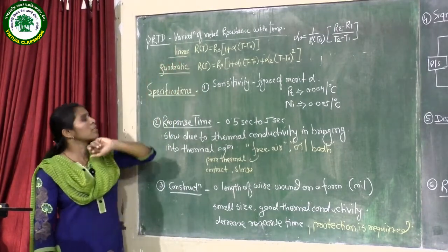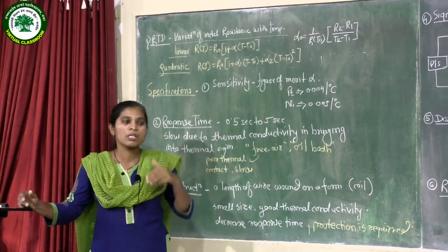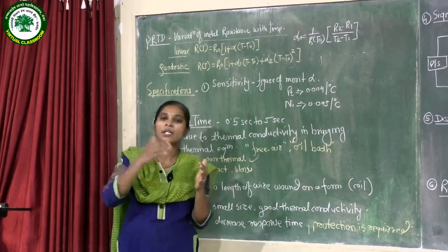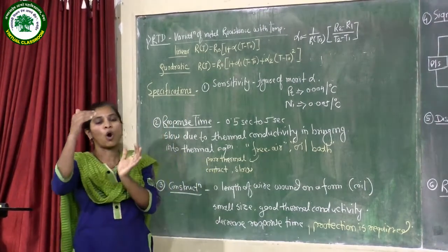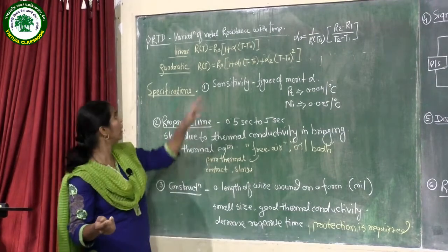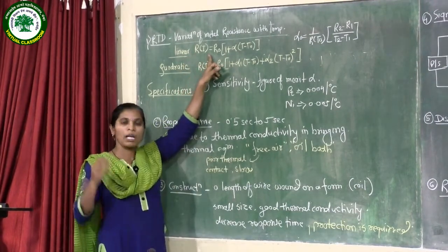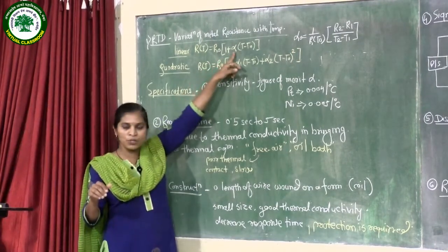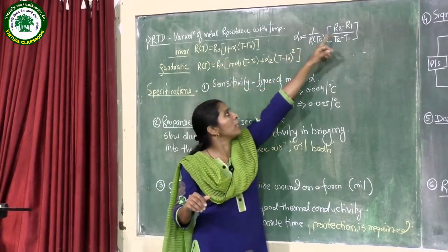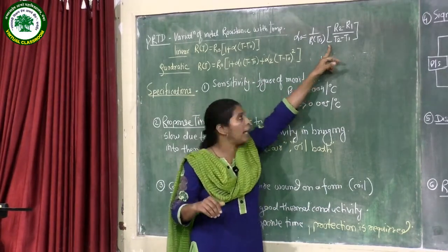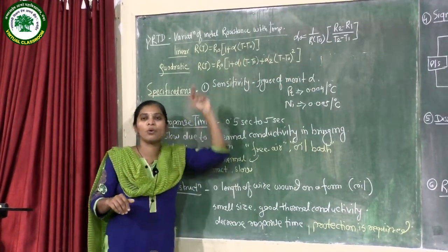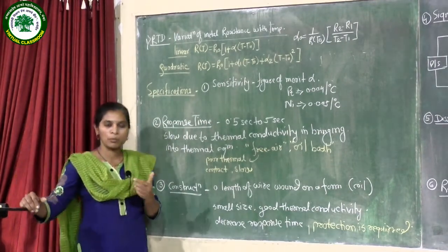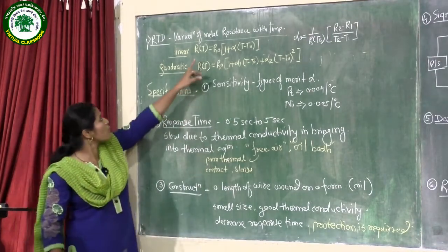Now, the limitation of this linear approximation is that we can use it only if our temperature is less than 200, or only for a small span of temperature. Later on we will see a problem based on that. And over here alpha is a constant, and this alpha or alpha 0 can be determined in this particular manner. Many a times this T0 is chosen such that it is located at the midpoint or central portion of the given temperature zone. So this was about the linear.